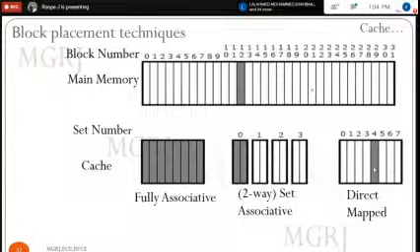From the designer perspective, making fully associative is the tougher job, because all blocks have to be mapped to all of them. So generating the control signal for each combination is very difficult. Designing the circuit and generating the control signals for fully associative is tough. Rather, in direct mapping you are mapping one block to one of the blocks. See, the first 8 blocks are mapped to the first 8, and again, repetitively, the second 8 blocks are mapped to the same 8.